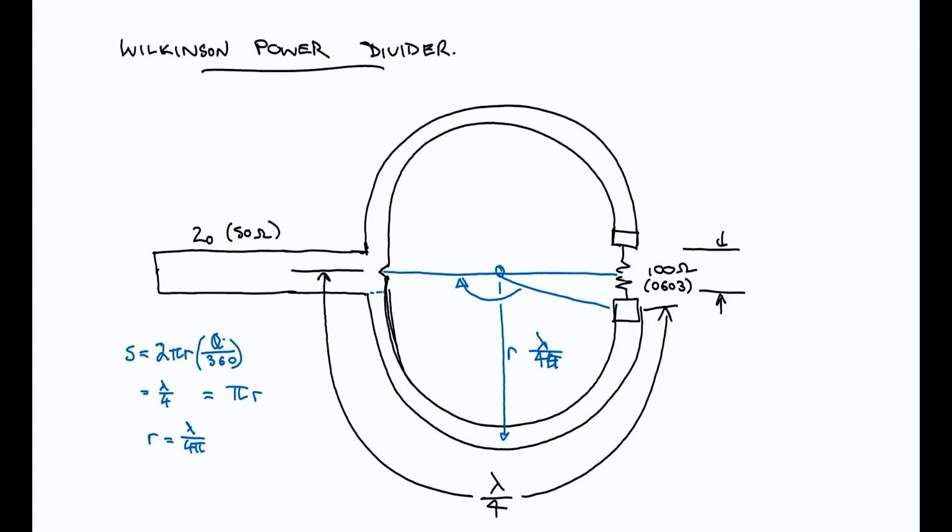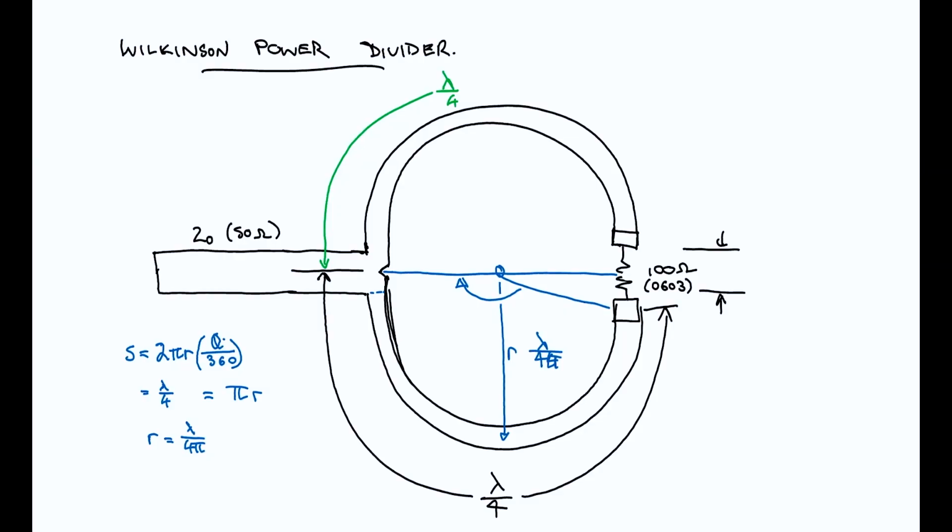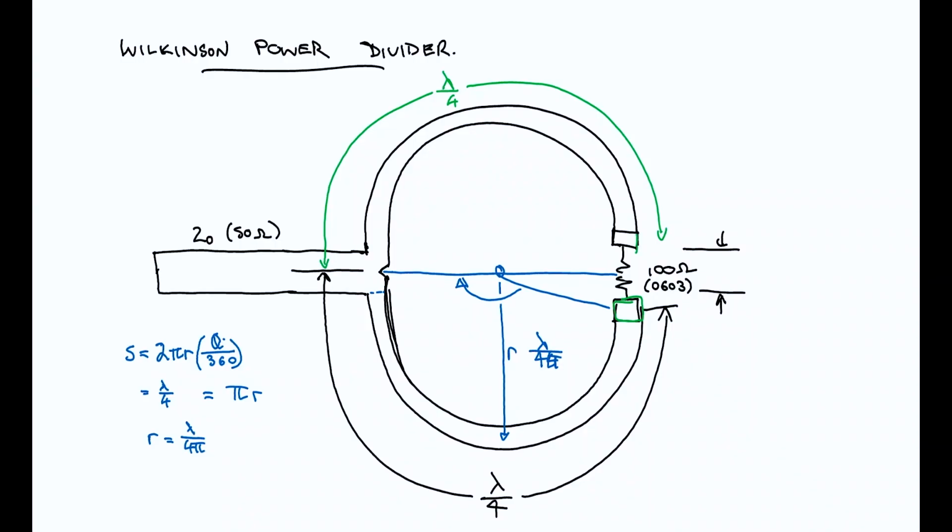It's very nearly 180 degrees. So what we're really going for here, just to make it super clear, is we have a quarter wavelength transformer times 2. These are quarter wavelength, and they don't have to be circular. You could go up and have chamfered corners and come around, but the actual path length of that transmission line transformer needs to be a quarter wavelength. And between them, on either side of the resistor's pads, from here all the way around to here is a half wavelength. Why?